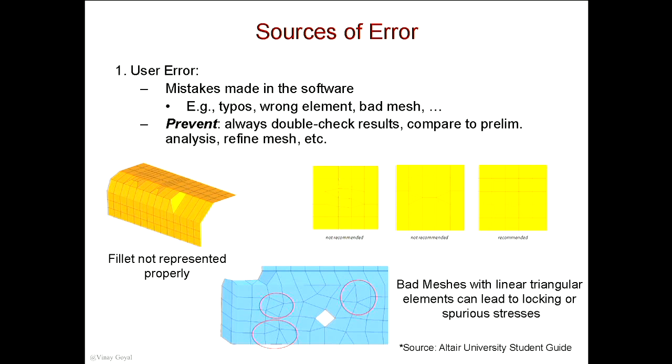But as you know, we've shown you that triangular elements can result in locking. You may have seen that in your homework. For that reason, you also want to be careful. I always look for typos. Units have been a big issue in my area of expertise. If you're given a model, make sure you know what units you're working in: inches, pounds, millimeters. Be consistent with the units, metric versus SI.